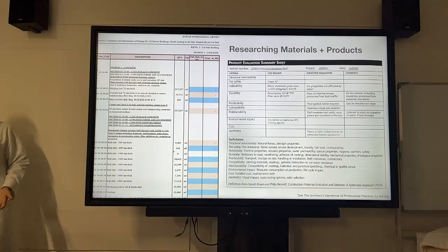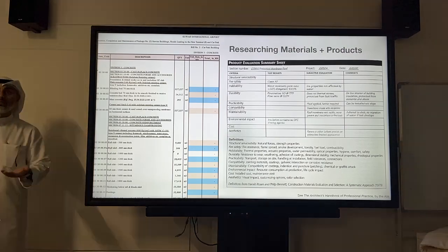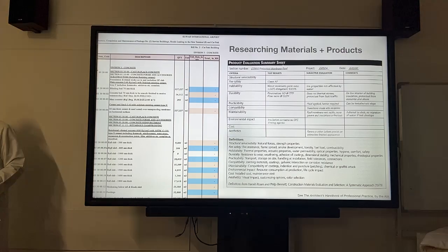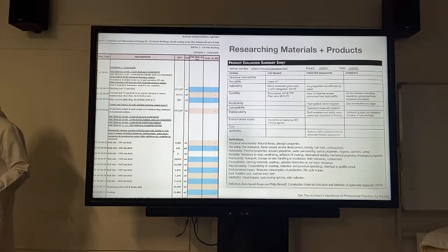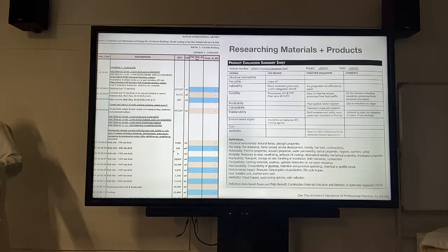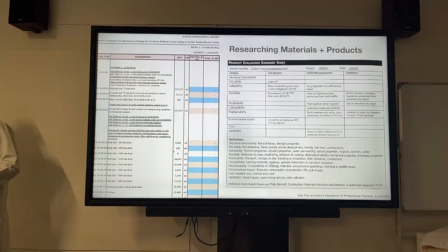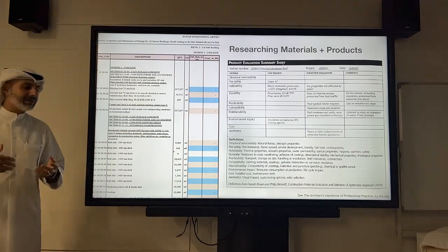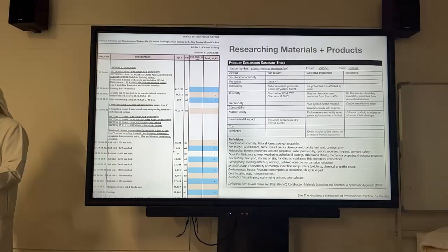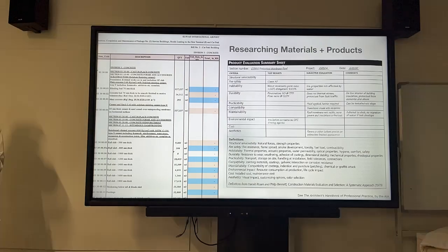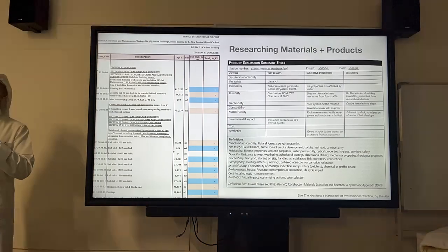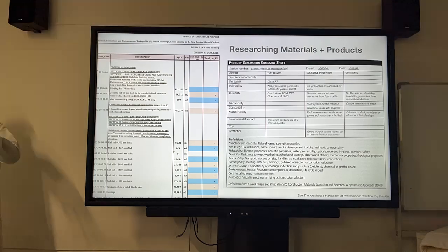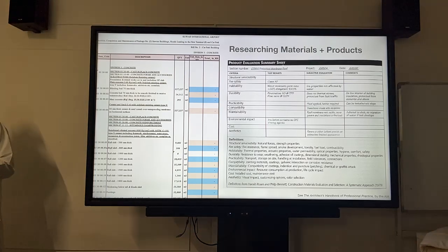And if I use this material, is it going to last 1 year, 5 years, 10 years? What do I need it to do? Practicability. So in terms of transport, storage on site, handling it, installation, compatibility. If I use it with another material, is it reacting negatively with it, or they're going together? Maybe one material expands too fast compared to another one. If I have, for example, stone and wood, is one going to expand more than the other and then damage the other material?